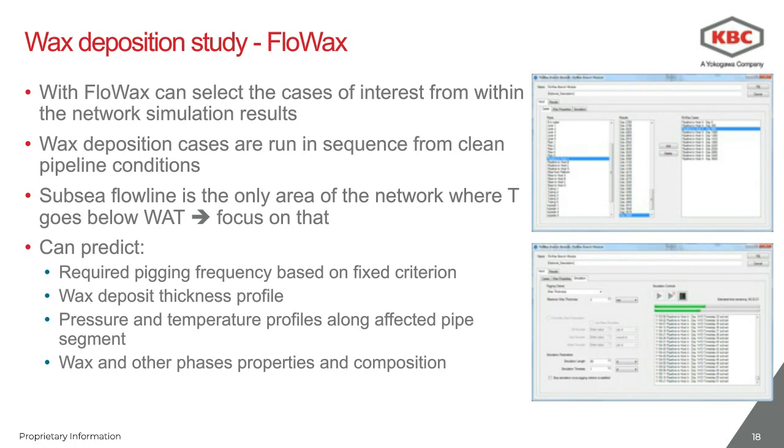I also know that the wax is going to separate only in the first 7 or 8 years of production, so I can simulate, pick up the representative cases from the life of the field collection and run the wax deposition study directly from inside the network model.